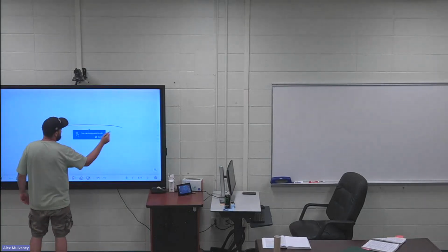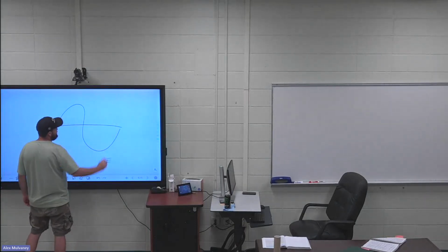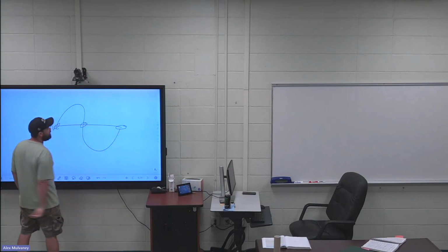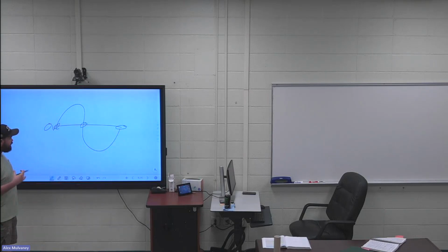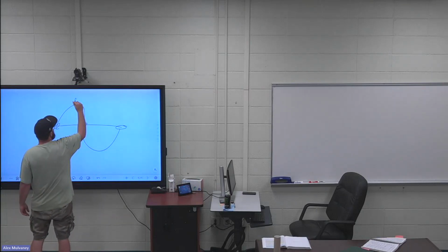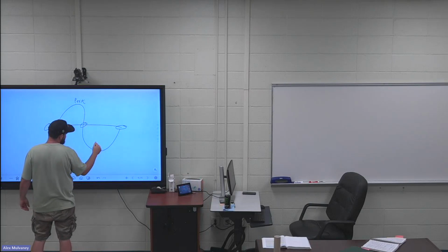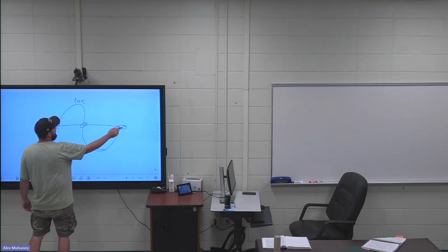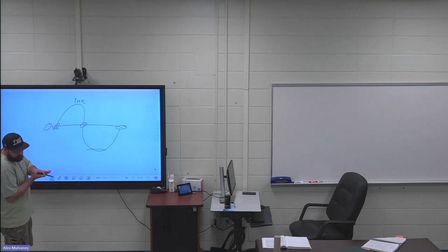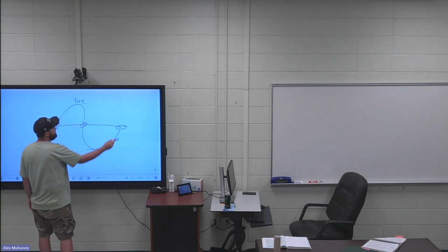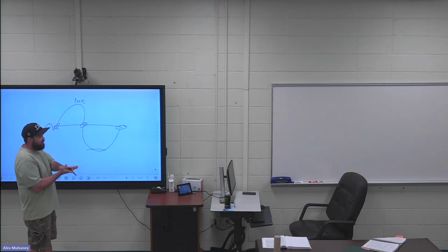Hopefully everybody remembers alternating current flows like this, right? So we have points of 0 volts right here, and right here. So if we have AC current flowing through a shading coil, this is going to be like one of your peaks, and then this is going to be the other one down here. But the points of 0 voltage mean that there's no electricity holding that coil together, and that shading coil makes up for these points of 0, and it holds it on there.